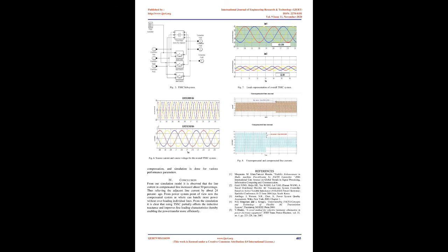The ideal series compensator is modeled by a voltage source, whose phasor is Vc, connected in the middle of a lossless transmission line. The current flowing through the transmission line is given by I = (Vs∠δ - Vr - Vc)/jXL. If the ideal series compensator voltage is generated